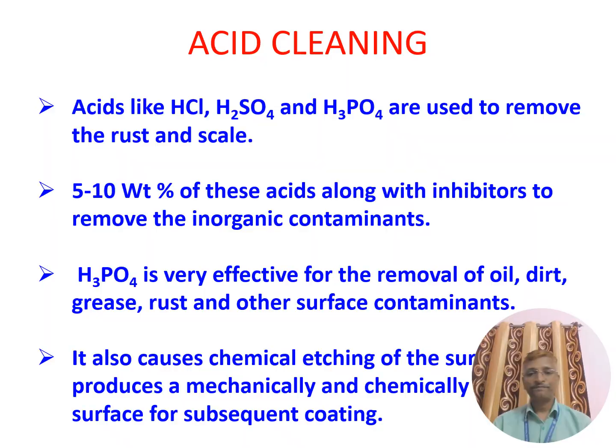Another advantage of acid cleaning is that it causes etching. So it does not only remove the dirt, oil and grease, it also creates etching. Etching means it creates some roughness over the surface. If it creates roughness, then when you coat afterwards, the metal will be coated very effectively. Whatever the coating material is, it will fit effectively on the substrate. You will get a very smooth coating.